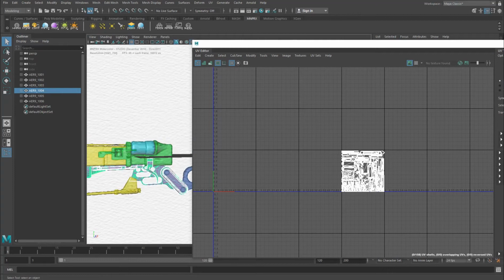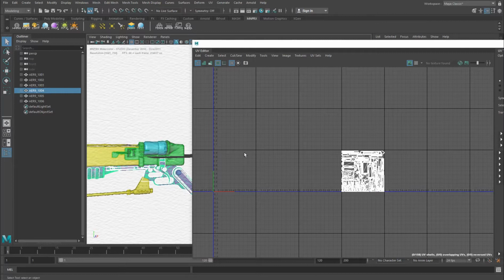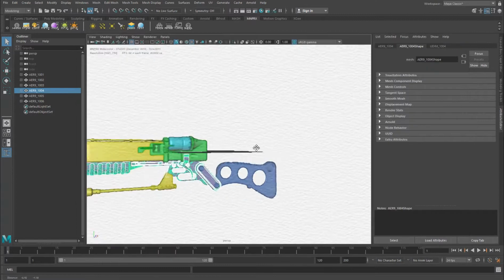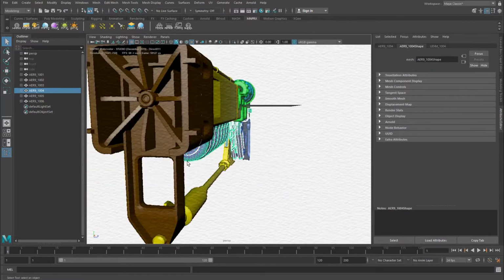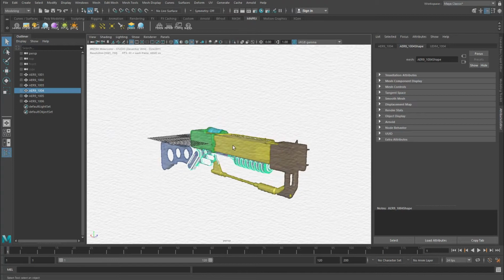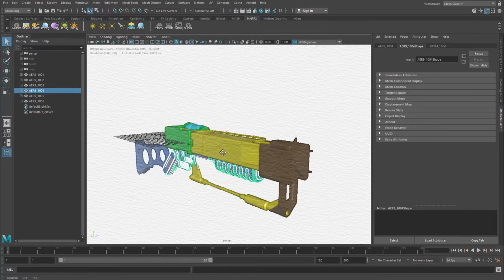In order to have more detail in certain parts of the object, you don't need to go between a 2K texture and a 4K texture that suddenly has 4 times more data. You could go from 2K texture to 2K textures and have the same amount of detail in the parts where you need it. Now, if your application works with UDIMs and you want to work with UDIMs in MNPRX, you will need to set this up manually, and you will therefore need to customize the ShaderFX graph for it. Now let's get to it.